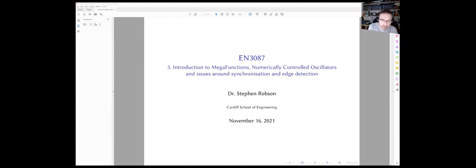For example, if you push the push button, you get a negative edge, and really you want to synchronize that with the regular rising edge of the clock. If you don't do that, you can have instability and your design might not work properly. So there is an industry standard way of resolving this problem called synchronization, and we'll discuss that towards the end of this lecture.